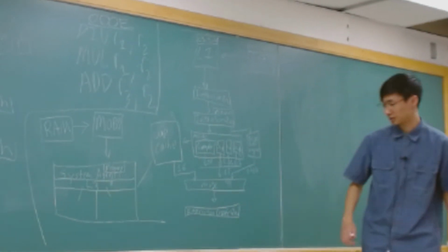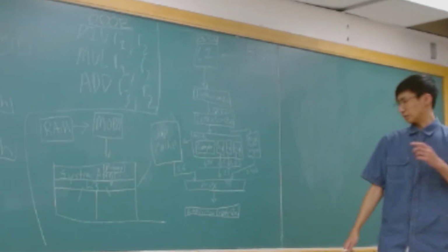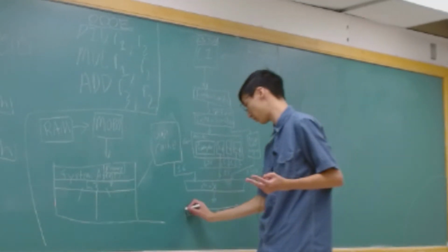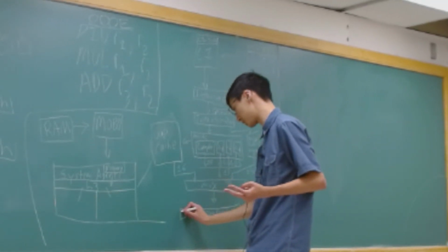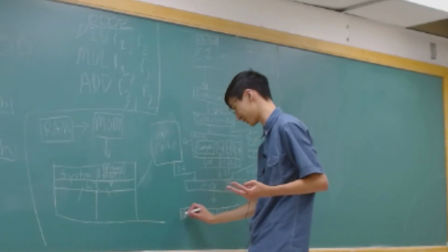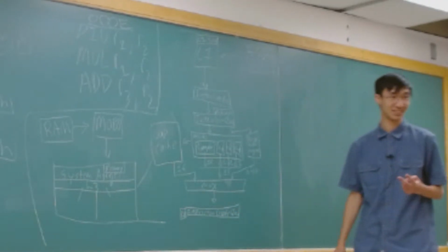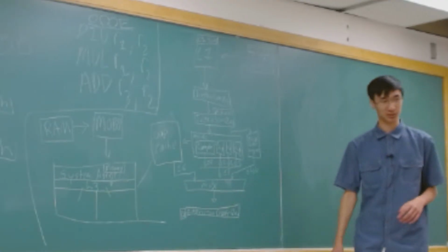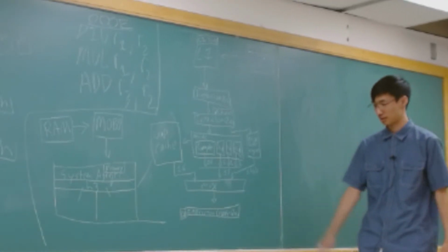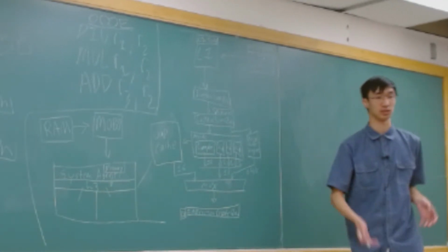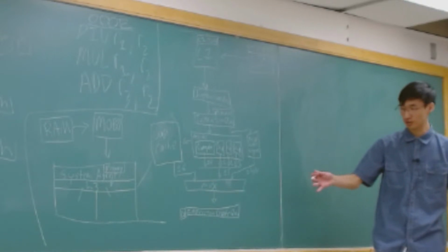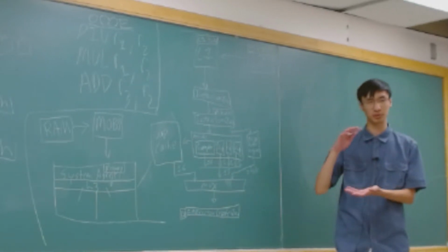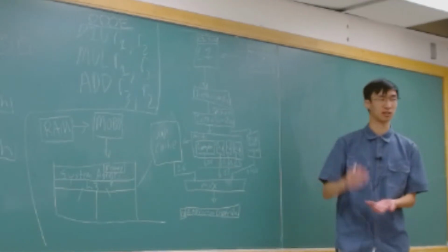The instruction decode queue will do two things. You have one thing called LSD. Yeah, the LSD. It doesn't exist on Skylake anymore. We turned it off using a microcode sequencer because there was a bug in it with the partial registers. But the LSD is a loop stream detector. It detects loops, and it kind of acts like a micro-op cache. It detects loops, and I believe it does like 40 instructions max or something like that.